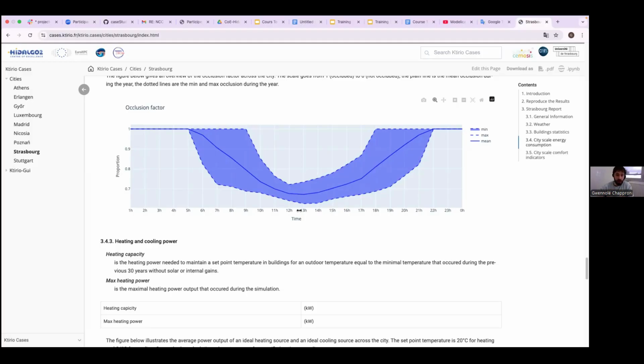As we are aggregating data for all the surfaces, we've got, as I said, the roof where we made a mistake and it doesn't receive any solar radiation. And you've got the northern wall, so we can't go to 0 because we aggregate the data of all the walls. And when we are calculating the shading factor, the northern wall doesn't receive much solar radiation, so its value is closer to 1.